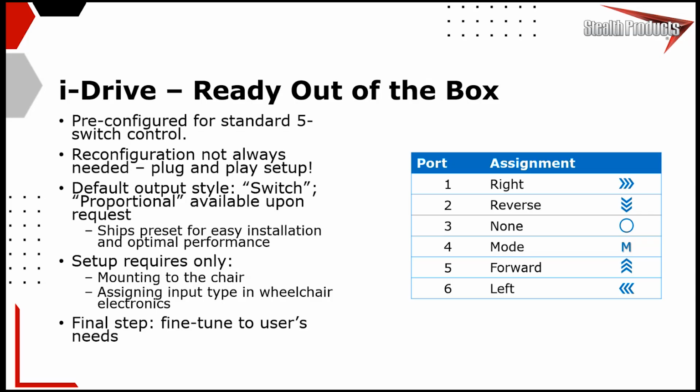You can change it to be a proportional forward and reverse, or a proportional left and right for some joystick control. You could set one channel to be a safety switch that would halt all outputs from iDrive when it's activated. It makes for a really cool feature when a head control driver might go into extensor tone. You could have them hit that safety switch and stop all of their output when they're not in control of what their head's doing.